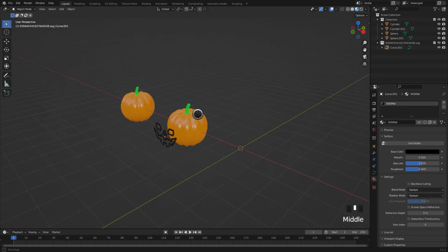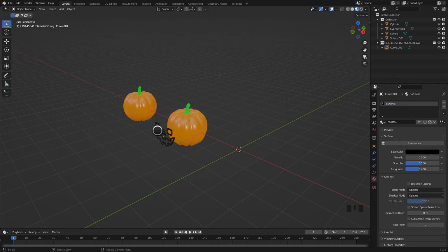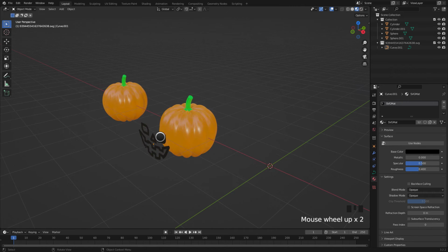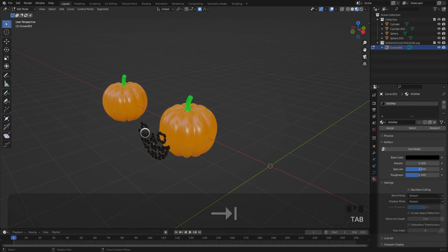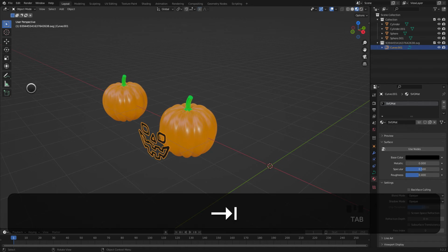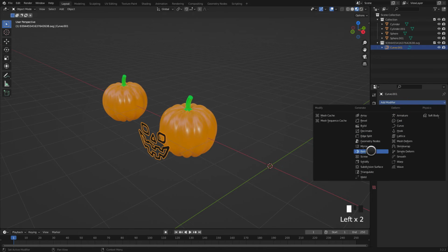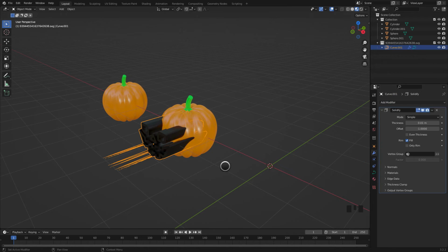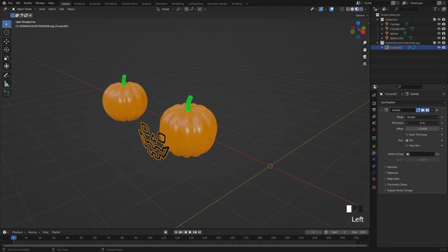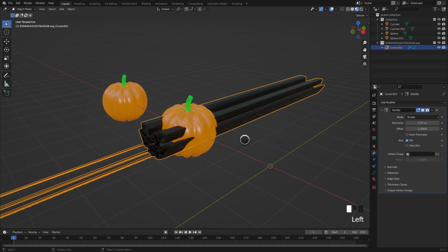These are curve files, means we imported from SVG image, so we cannot extrude using edit mode. We cannot extrude that. So there are two ways to extrude this one. First one, add a modifier solidify. Okay, and change the length, thickness. You can extrude.